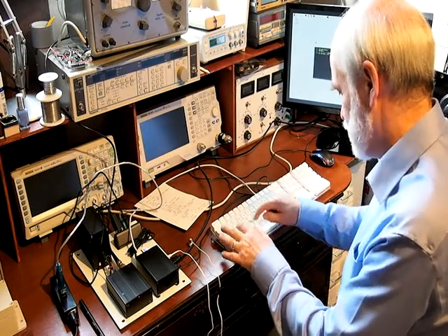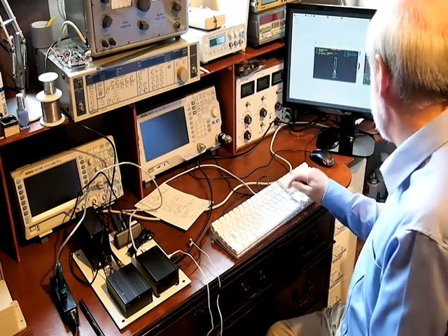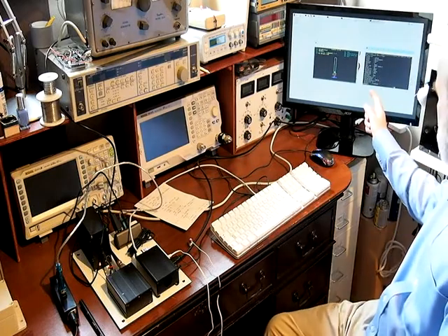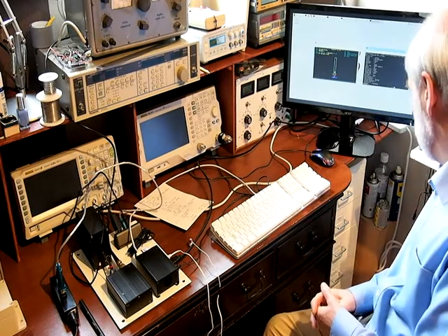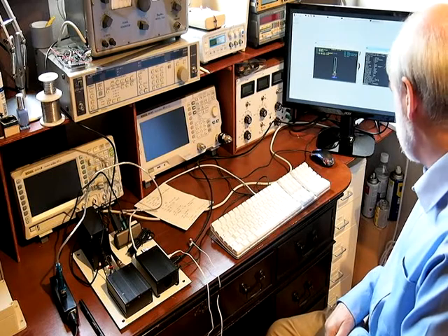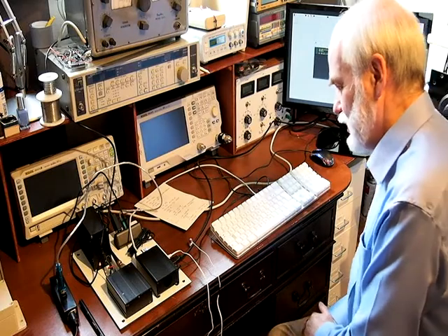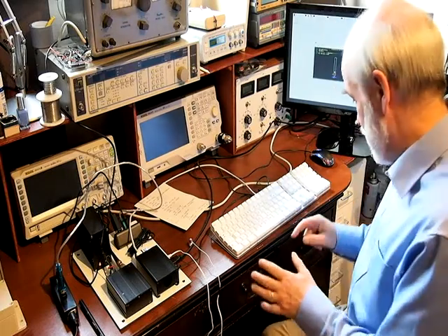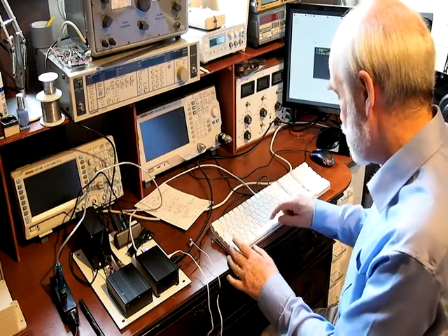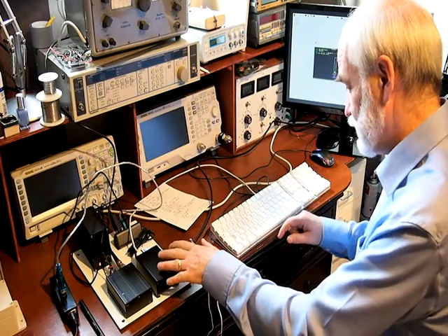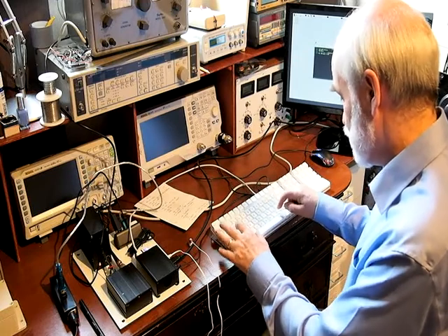There we are, and then we will record a sample of audio using arecord -vv -fdat foo.wav as the file name. And that's recording now, so we're showing a level here of about 18%, so that's fine. We're nowhere near limiting. The level is set correctly. That should be enough. Control C to exit, and then to play back we use omxplayer -o local for the sound to come out of the Raspberry Pi jack plug, not the monitor, and then the file name foo.wav.